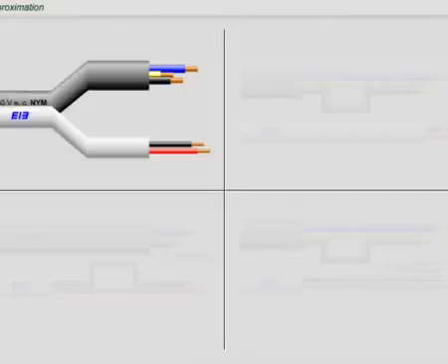When installing mains and bus cables, 4 different types of installation must be distinguished. First, mains cables and bus cables may be laid directly next to each other, provided that both cables are sheathed. Second, isolated single cores of a mains cable may be installed directly next to the sheathed bus cable.